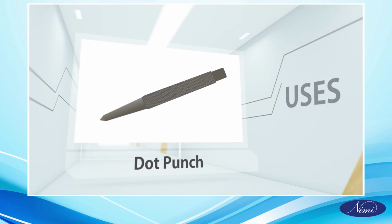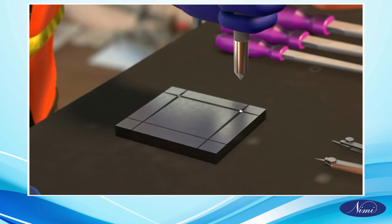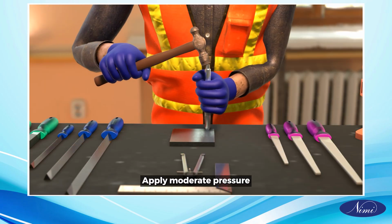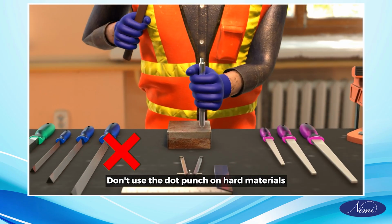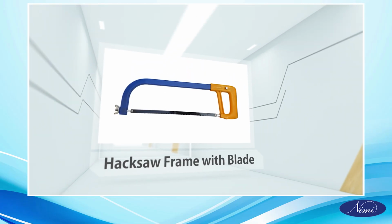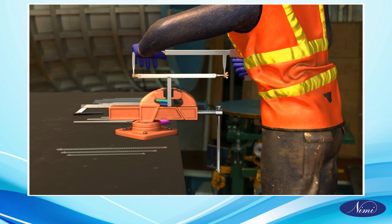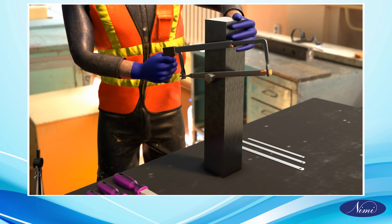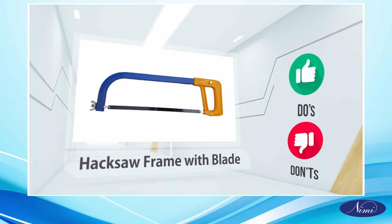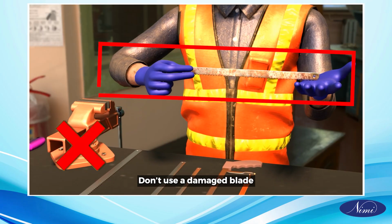Dot punch uses: marking locations for drilling, centering workpieces. Do's and don'ts: apply moderate pressure. Don't use a dot punch on hard materials. Hacksaw frame with blade uses: cutting metal, cutting bolts and screws. Do's and don'ts: choose the appropriate blade. Don't use a damaged blade.